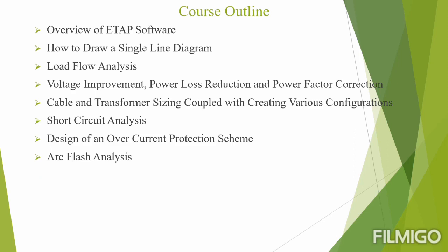Therefore, the analysis is necessary to determine the nature and frequency of occurrence of the arc in order to prefer suitable methods for protection purposes, thereby mitigating the consequences of an arc flash. After that, we'll be going into the design of a differential protection scheme. Now, a differential protection scheme is basically for transformers, where we'll be considering the effect of an internal or external fault, and we'll be configuring differential relays to protect the transformer against these faults.